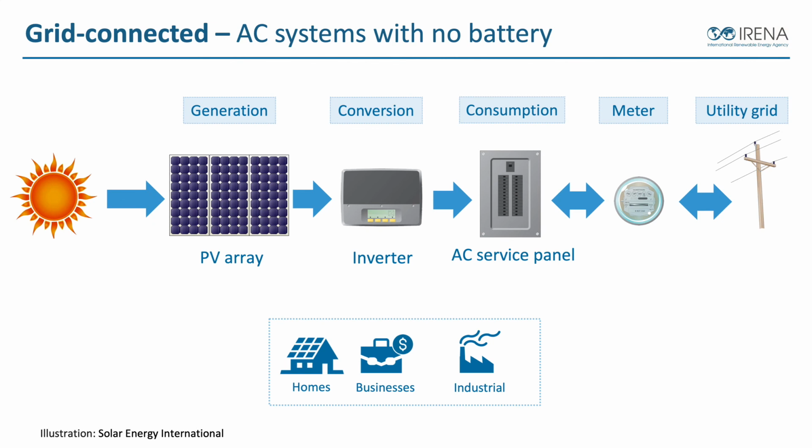So it's meant to synchronize with the electrical grid, take the DC in, and make a perfect AC waveform that perfectly matches our utility's voltage and frequency. And we need to specify that inverter for that purpose, where it is able to take the solar and export it into the electrical grid and sell excess energy if our utility company allows us to.